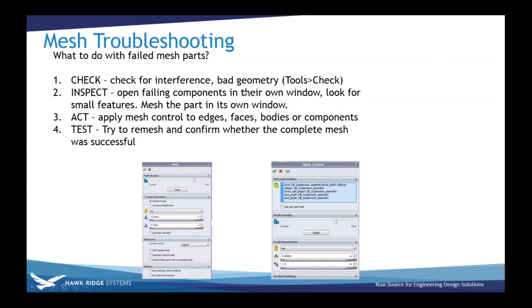The other question I haven't put here, but I ask myself, is: do I need this thing? Do I need the Phillips slot on my screw there? Is the thread on my bolt important to the strength of this object, or can I represent it with, say, a bolt check?